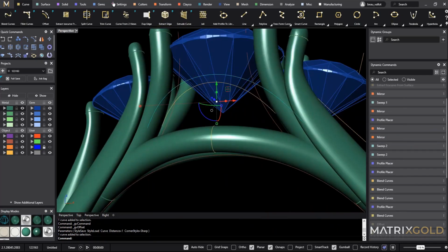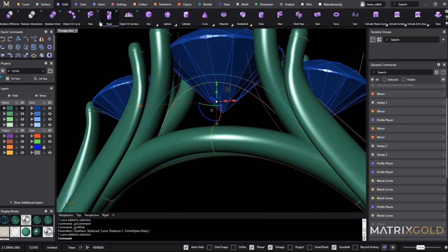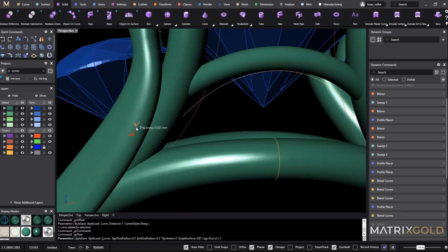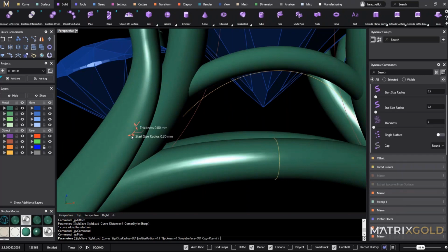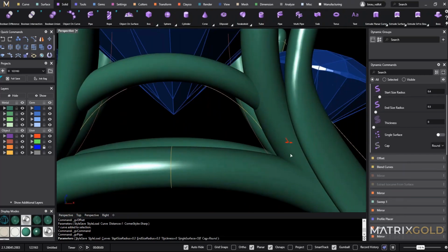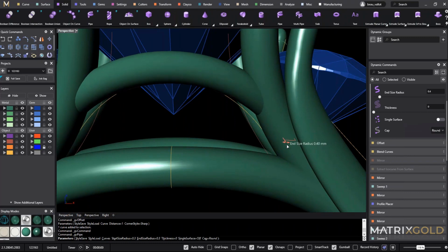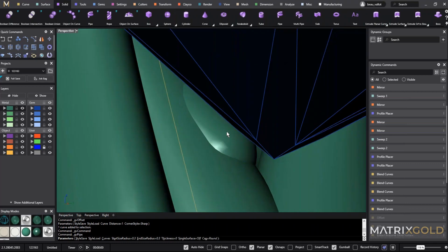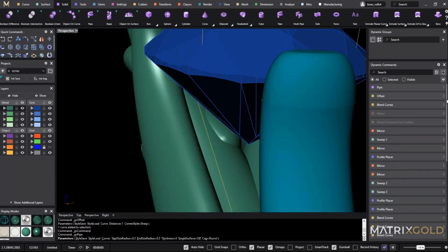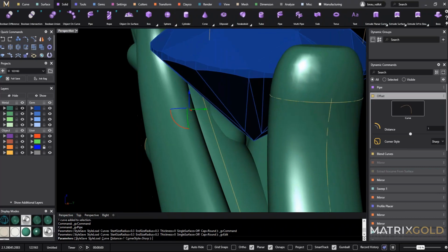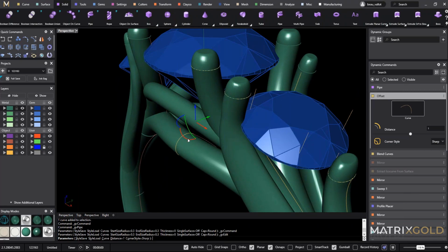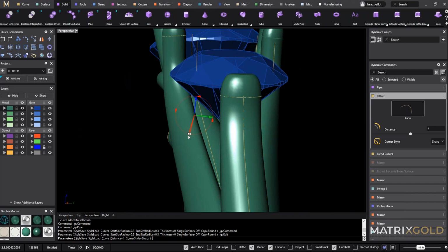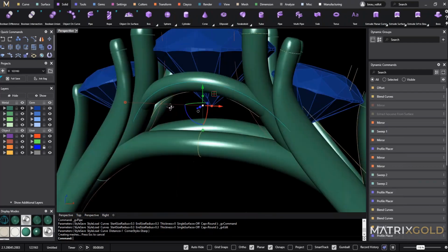So now we can pipe it. So I can go to solid, select my dynamic pipe, and we can increase the diameter. So I can right click. So you see it's coming through a bit right here. That's pretty simple to fix. You just come here, select the offset. Without changing the look too much. And right click when you're done.